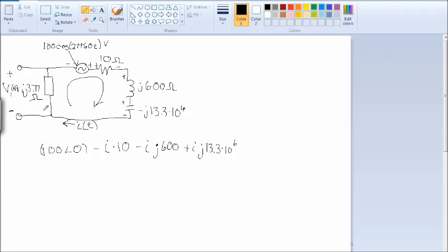And then over here we are going in the opposite direction again, because now we're entering the negative and leaving the positive. And the reason we're doing that is because that's the way the problem defined the voltage. So this one will be a plus, plus I times J 3.77. So we just did a full loop of all the voltages. Remember, the voltage law says that sum should all equal 0.